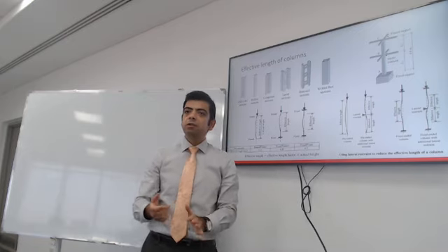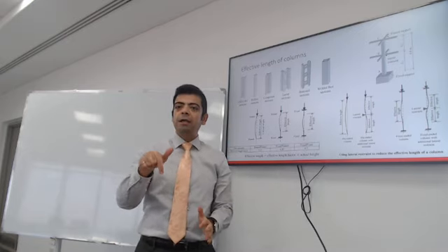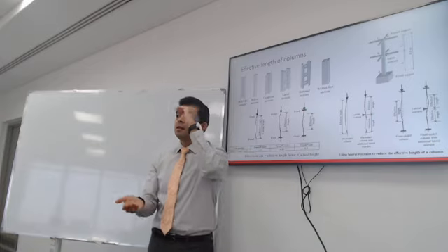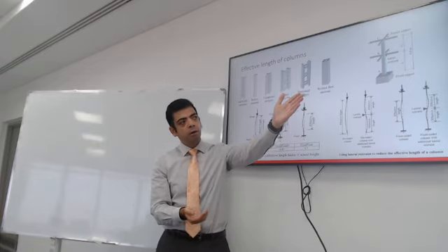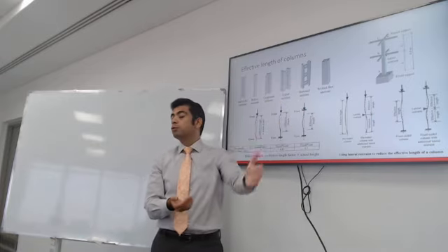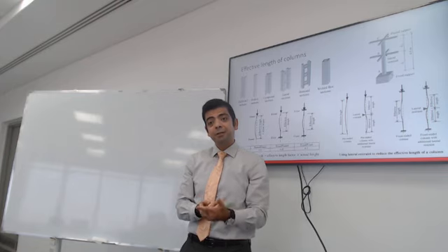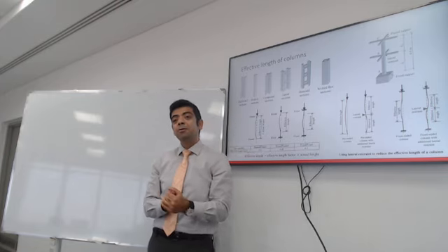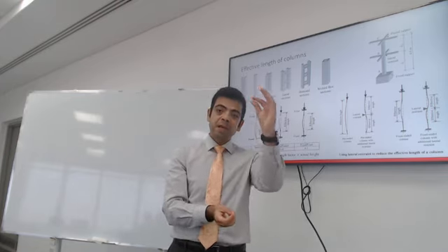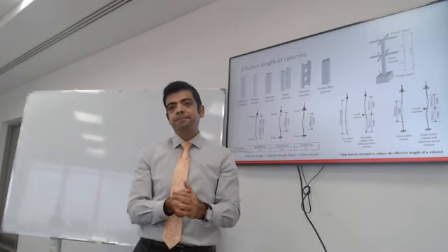So let's say you're designing this building that we're in right now. How do you get the effective length of the column at the corner of the room over there? How do I know whether it's pinned or fixed? You are the designer. How do you design a column that is pinned at the top or fixed at the top?